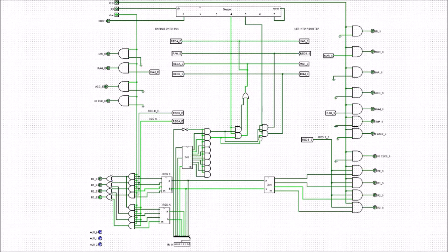So the bottom two AND gates here have got high inputs here. Now they've got a high input because we're choosing this particular one, which is the store instruction. Now the top two AND gates, those will go live whenever we choose the first AND gate here, which will happen whenever we do the load instruction, which we'll see just in a minute. So you can see here these two bottom AND gates, we're in step 4 at the moment. So this one and this one is going live.